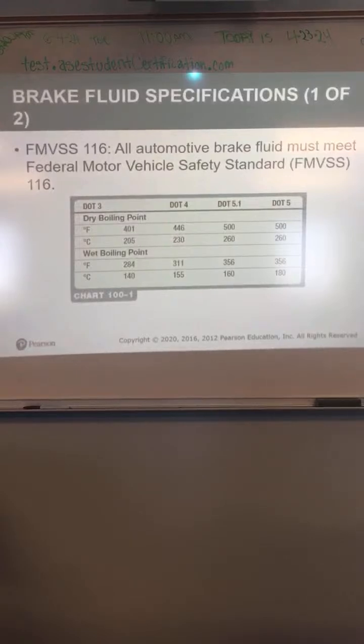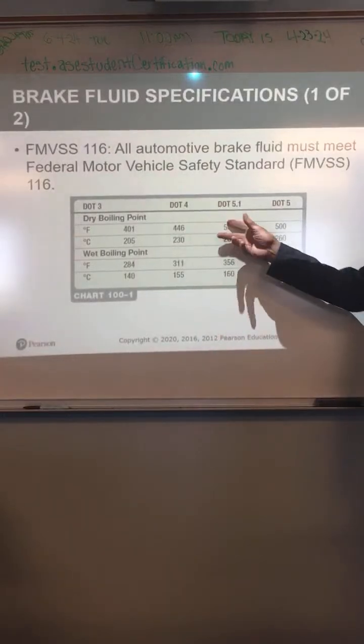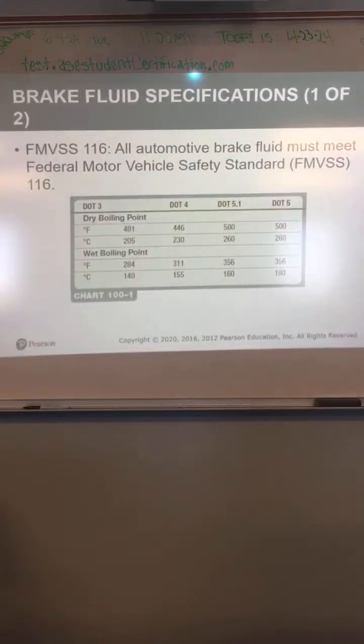All brake fluid must meet Federal Motor Vehicle Safety Standard 116. There are different types of brake fluid, the most common ones being DOT 3, 4, and 5.1. We'll go through what each one of those means. It gives you the boiling point on them, wet and dry.